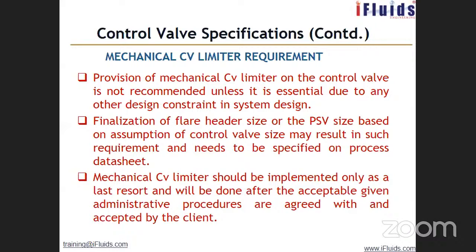It's not there. It is only for specific requirements where we want to restrict the capacity of the valve, so that it does not reach a higher value than what you desire. Similarly, finalization of the flare header or the PSV size based on an assumption of control valve size may result in such a requirement. This usually comes in the flare system lines.